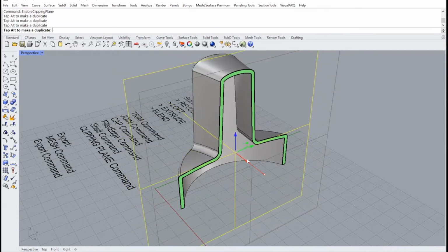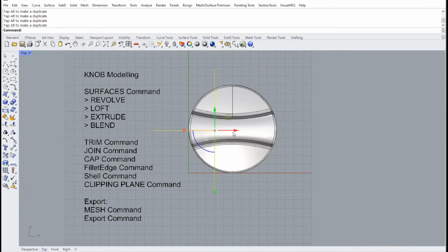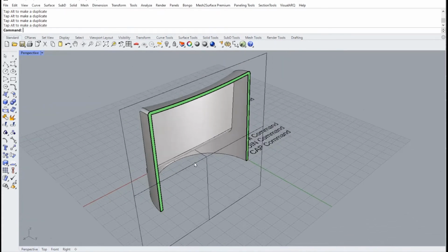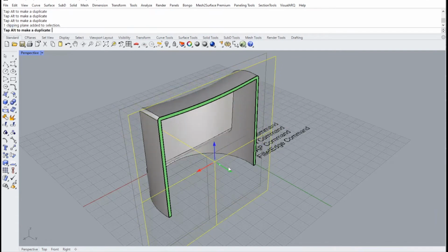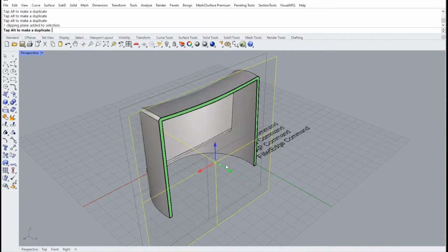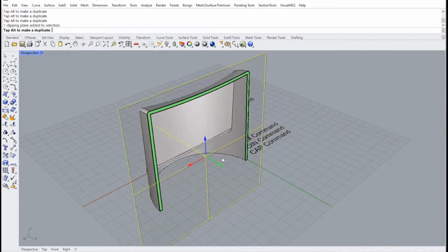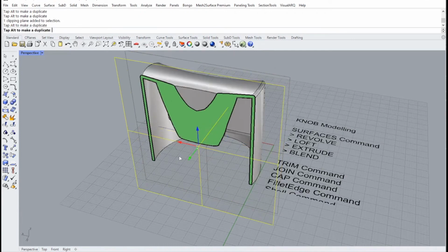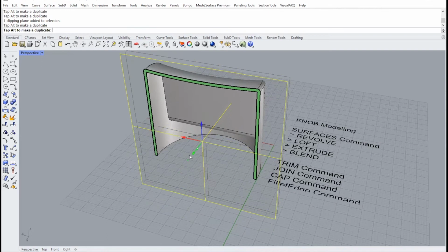Okay, so that's clipping plane. Of course, if you go to the top view and try to adjust it to the center, use the gumball and say you want to have it 90 degrees. Let's look at perspective again. It's the other way around. Clipping plane is very useful, but at the same time, your text will be missing as well following the clipping plane.